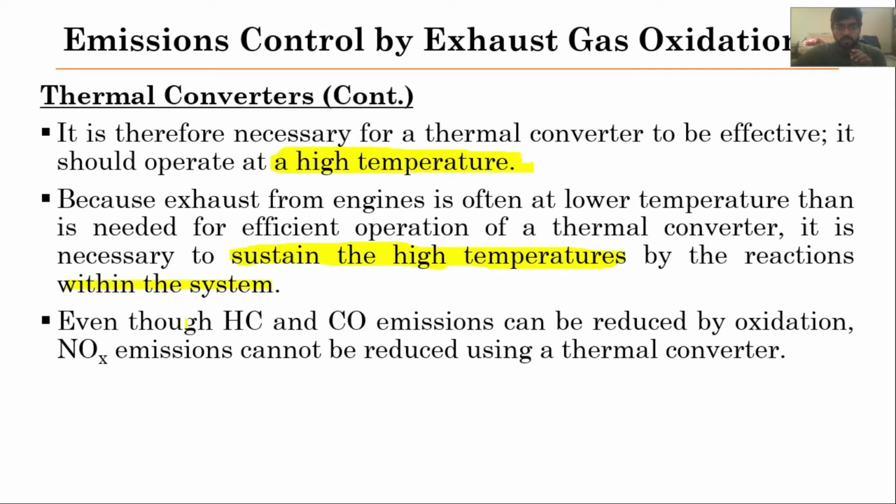As I mentioned earlier, thermal converters control hydrocarbon and carbon monoxide emissions by oxidizing them, but they cannot control the NOx emissions. If our engine is operating at very high flame temperatures, some NOx emissions are present, and to remove them there must be some additional device.